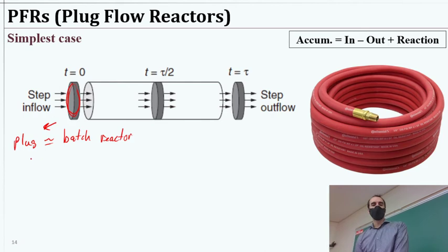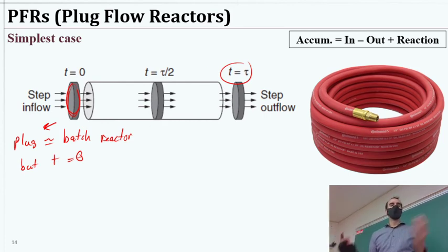And as we'll see when we do the math later, the difference here is the time is equal to the theta, or in this case, the tau. They just wrote it tau, I'm writing it theta. I'm meaning the same thing, right? So t is equal to the hydraulic retention time. That's how long the water stays in the reactor. That's our design criteria for a plug flow reactor, because that's how much time this little batch of water spends going through the system, okay?